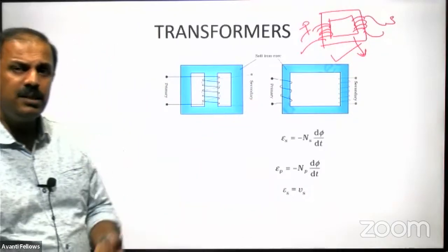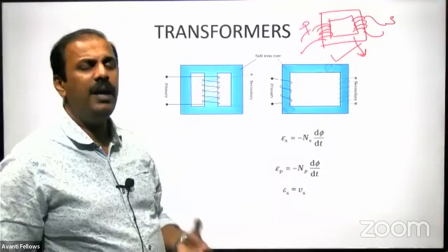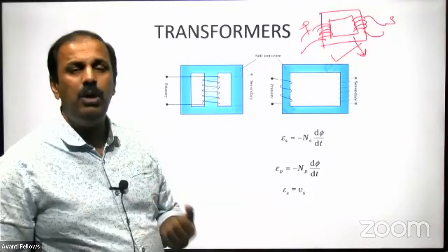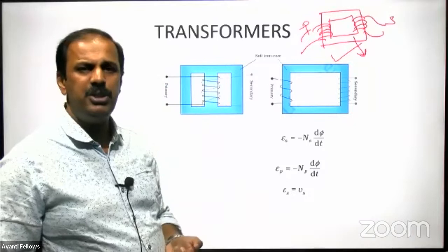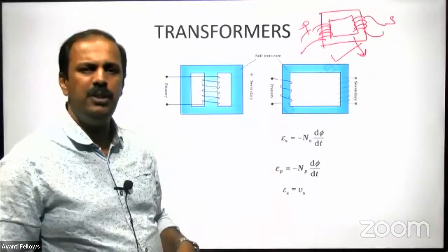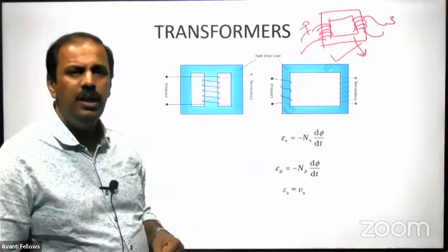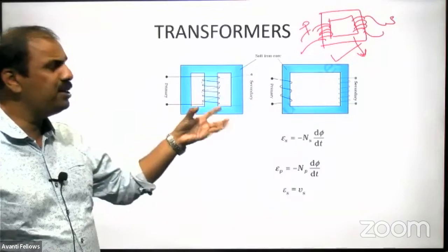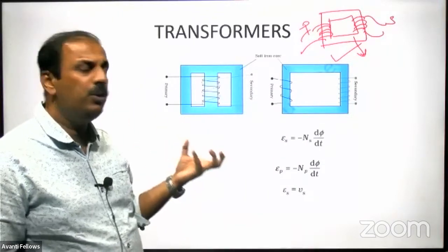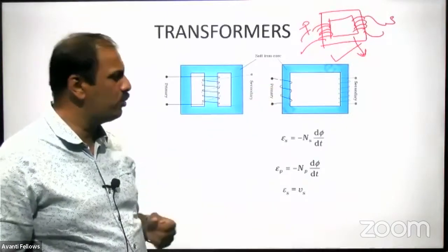That is the answer for the question that generally comes: why is high voltage AC used for electrical transmission? Why high voltage is used in current electricity, you might have studied: the transmission loss is inversely proportional, so that's why high voltage is used. Why AC is used? Because using transformers for increasing and decreasing the voltage is possible only with AC. For DC, we cannot use transformers.